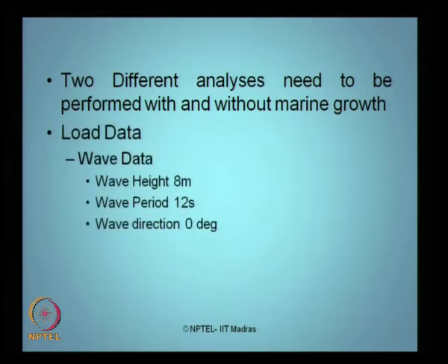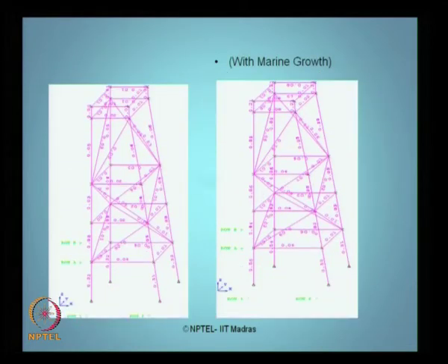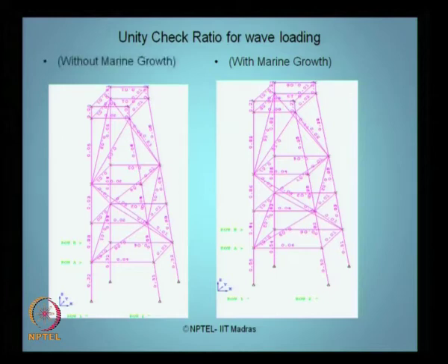The load data what you generally use, or what has been used in this specific example, is a wave height of 8 meter, wave period of 12 seconds, and of course, you should check it for different approach angles. We start up with 0 degree here. So, this is how you will see both the figures generated with and without marine growth. The left one what you see is without marine growth and the right one is